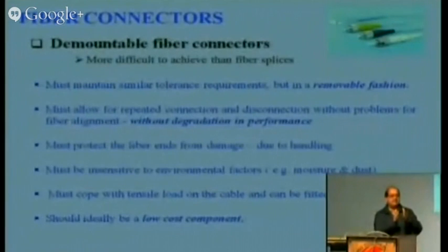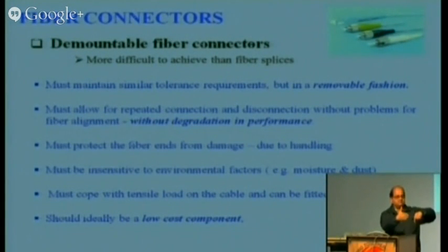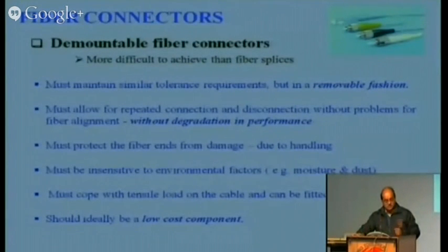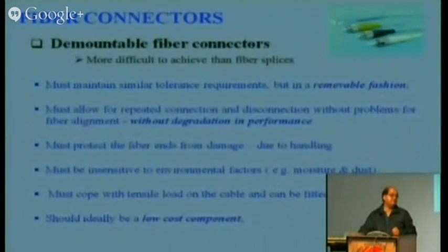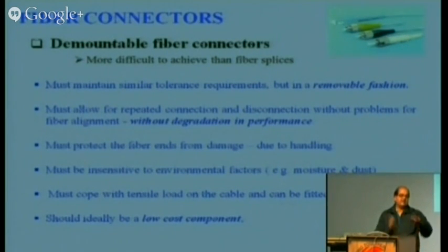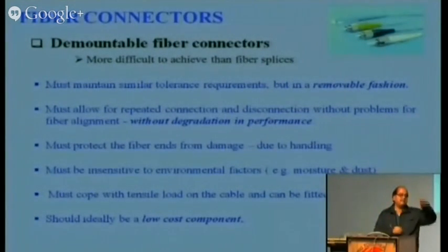So something should be there at the connector so that the fiber is not exposed. It must be insensitive to environmental factors. Moisture and dust should not deposit on the fiber. It must cope with tensile load on the cable and can be fitted with relative ease. If there is pressure on the connector, it should have the strength to bear that pressure.